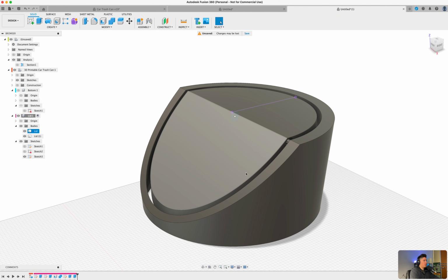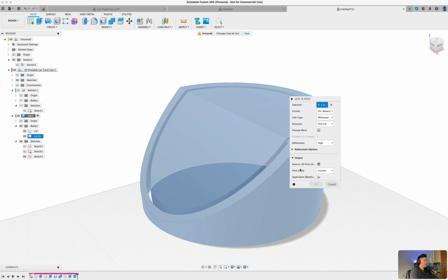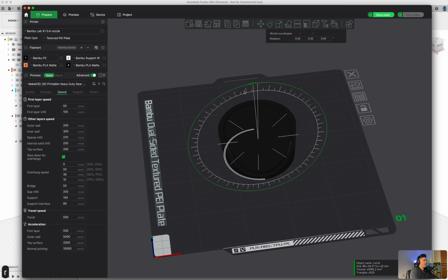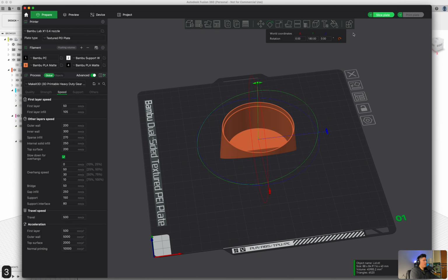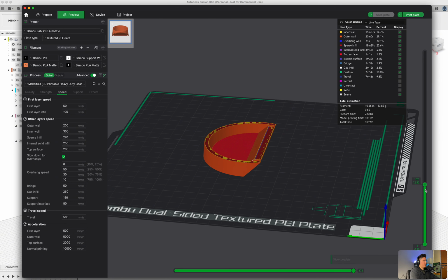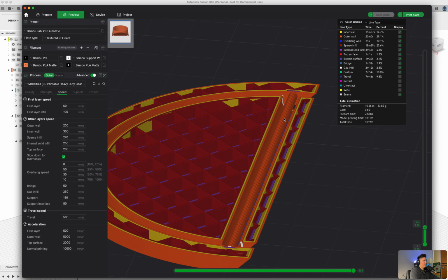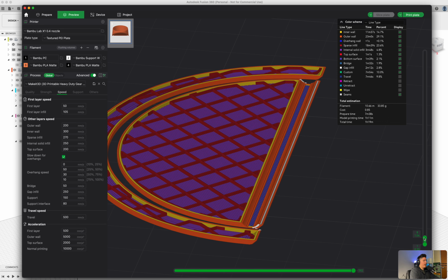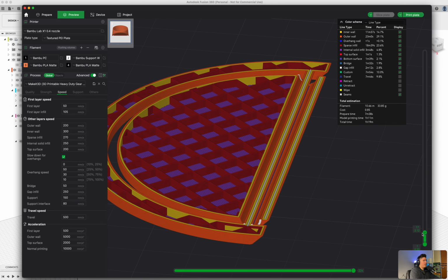So if we were to import this to our slicer, let's go ahead and reorient this. And now we're slicing it. You can see if we were to go down into around layer 26, 25, that now our pin sits right here in the middle with enough of a clearance for this swivel piece not to touch our pin. And your printer should have no issue printing this, even though there is a slight overhang, as most printers should be able to handle printing moving parts like this.